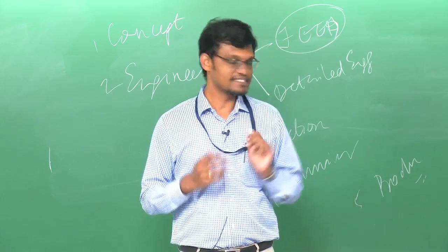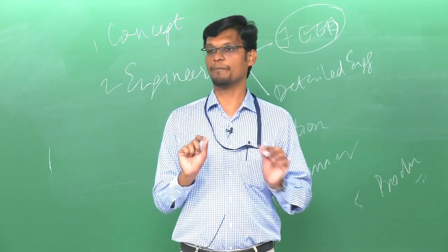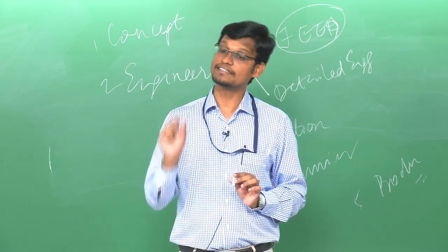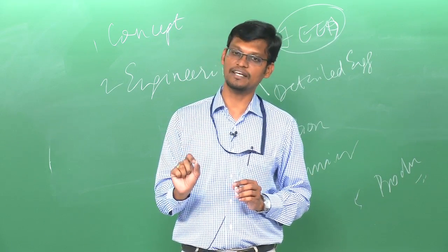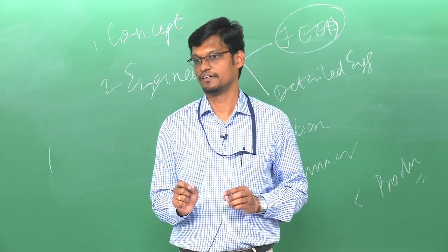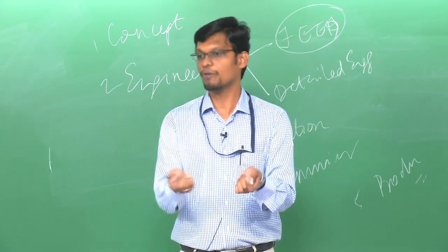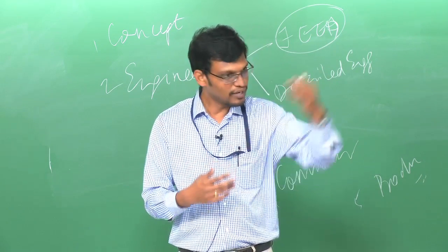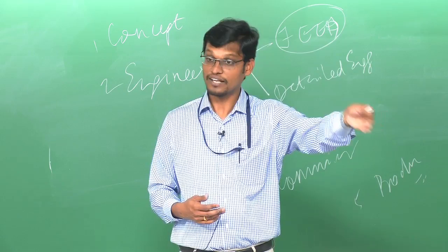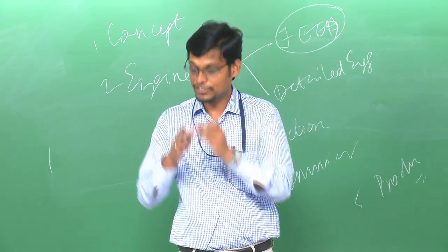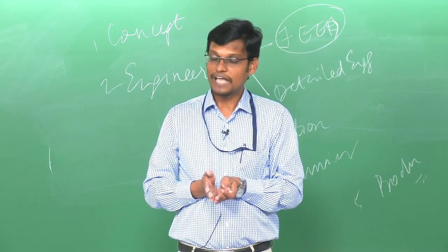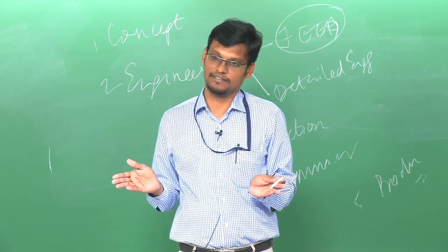But if you ask me, a safety audit is not one of the best techniques for a process hazard analysis. The reason being, it is an audit, and any audit for that matter is a sample audit, correct. Like you go to a particular plant, you have a time limitation, you are there for 2 days or 3 days, you look at what a particular operation is done, on that particular day how is the operator behaving, and based on which you are trying to frame your observations and recommendations. So, that is not going to be a foolproof method, okay.